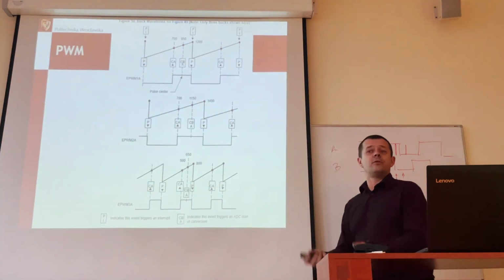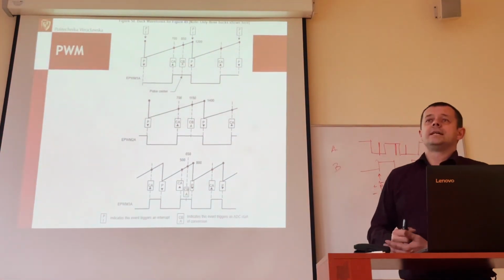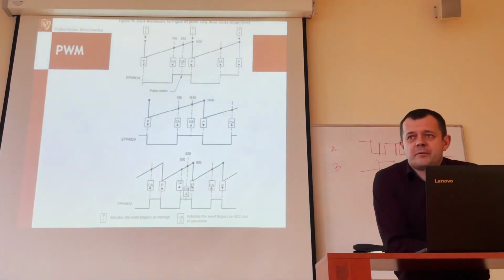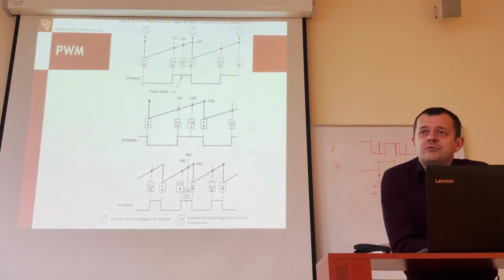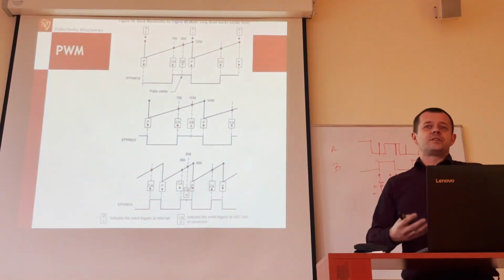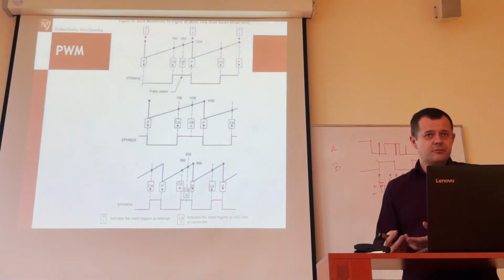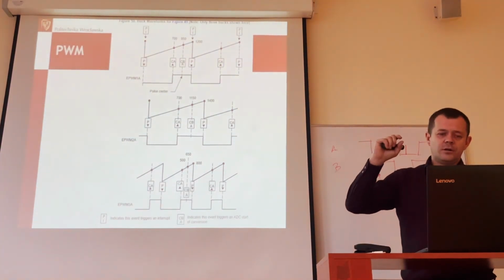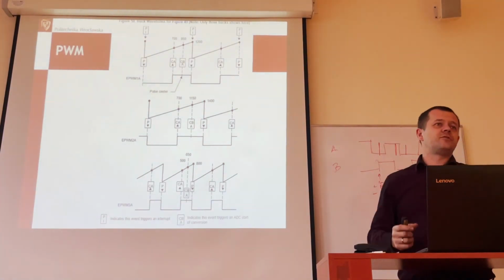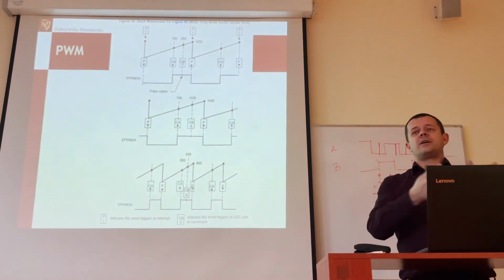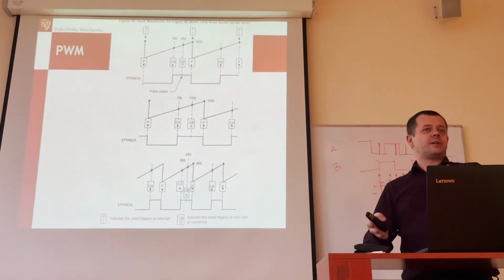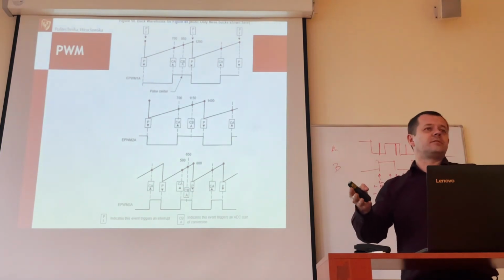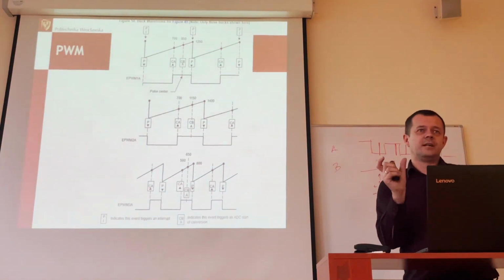That's the way how we avoid today in microcontrollers the necessity. We talked about the linear and switching power supplies. This is one of the methods how to be able to use switching power supplies today in microcontrollers, even if a very low noise or very high precision of conversion is required. So we are switching at time t1, and we are converting always at time t1 plus epsilon, or plus some delta.